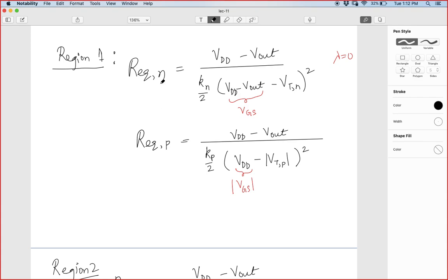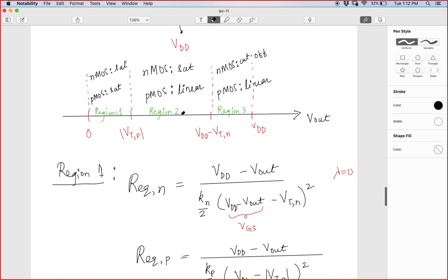If we see individually, you'll see that there is a lot of variation in the impedance. But if you see collectively, the parallel resistance, it's not constant, but it seems to be constant with the voltage. In all this region, it seems to be a little flat. Whereas individually, the resistance varies very rapidly with change in V out. Because of this property, the combination of the NMOS and PMOS leads to a quite constant resistance. That's why this transmission gate is quite widely used in VLSI design.